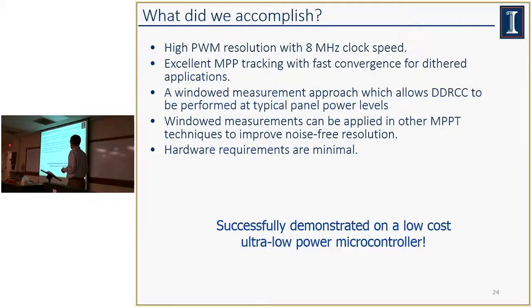The windowed measurements can also be applied to other, for instance, perturb and observe maximum power point tracking techniques, and it will be easier. So this windowed measurement technique may be even more helpful in less aggressive MPP tracking techniques.